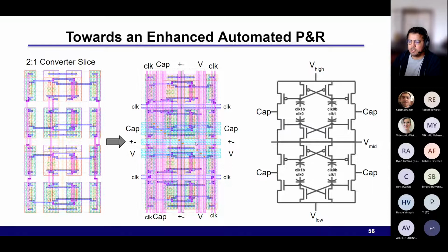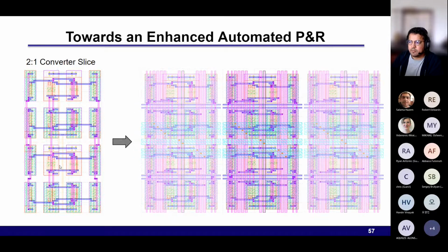When you put this mesh on top of it, the goal is that when you increase the size of the transistor, you'll still be able to connect correctly to this mesh. That was a bit of work, but it's actually reusable, so it can be used in other designs like the SAR ADC or even the LDO. So that's the current approach we're taking.